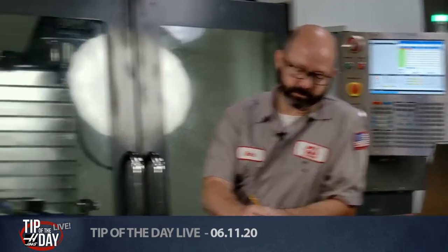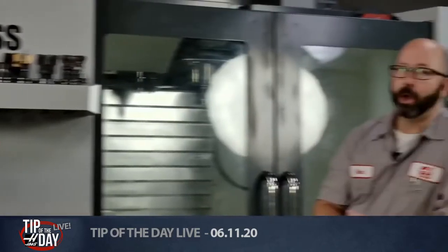Cool. Now here's a question from a couple weeks back. Y Chef asks, I've been wondering what type of tool compensation you guys use and how you use it in conjunction with tool diameter probing. Can you update the wear table instead of diameter? Short answer is no. So the question is, can we update the wear table instead of the diameter? It's something we've looked at over the years. Right now, I've run some machines where I'll go into the Renishaw macro, I'll change a couple variables so it, when you probe a tool, let's say I've got a 12 millimeter tool and it measures at 12.05.